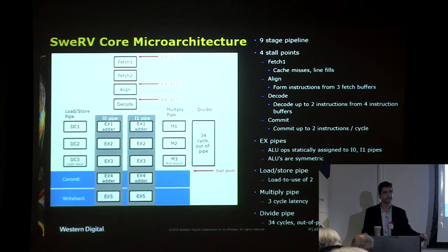This is a comment to that question. Usually, when you say an interrupt, it's an external interrupt, and the external interrupt can never be a synchronous event. There is no way you can make it synchronous. So as long as you're talking about external interrupt, the 9 pipeline stages are pretty much independent as far as I know. Yeah. Correct, I agree with that.